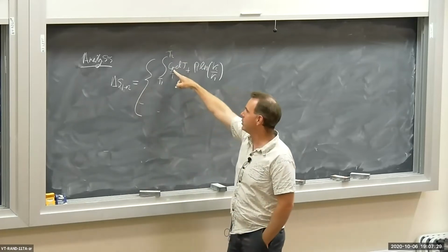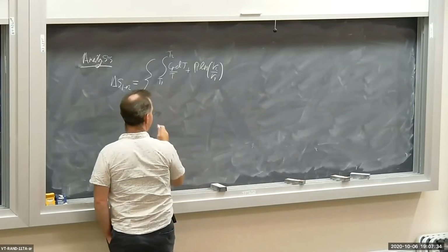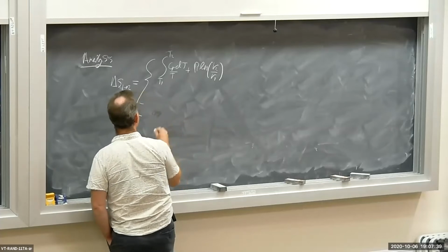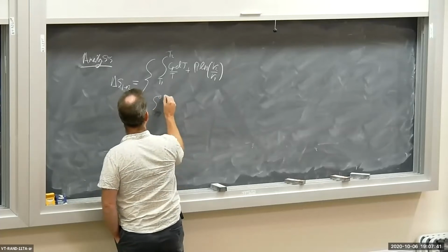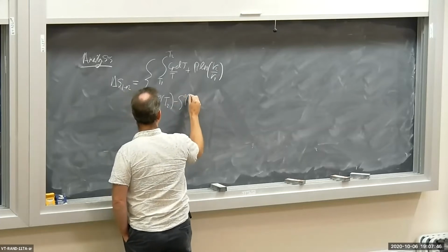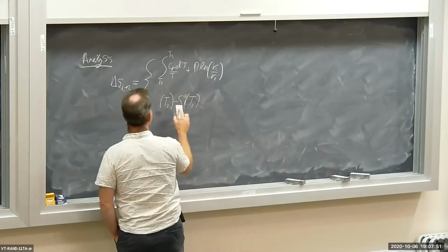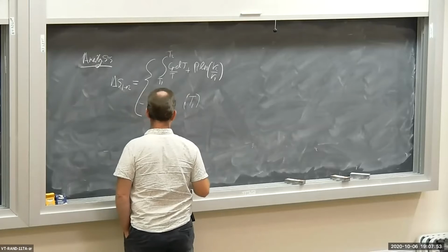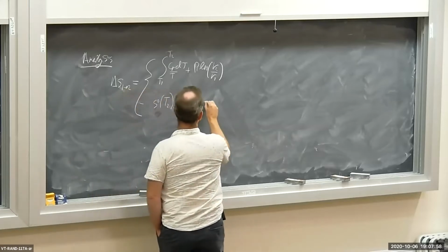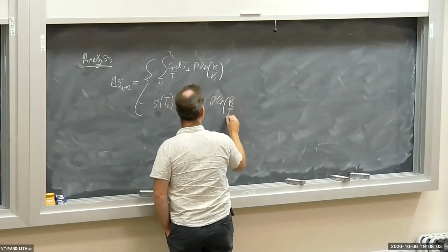I don't know how I'm going to actually evaluate the integral given that specific heat is variable. Or I have the version involving enthalpy and Cp and S naught. So I also have this version, S naught evaluated at T2 minus S naught evaluated at T1, minus R ln P2 over P1.